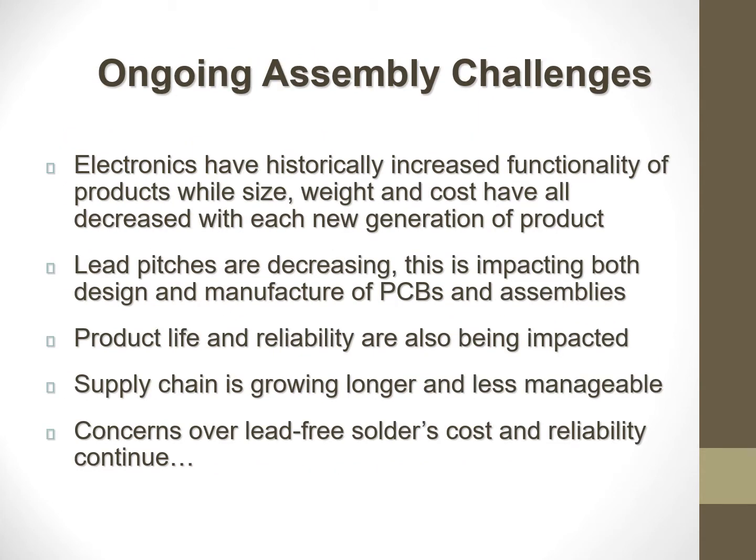There are ongoing challenges in terms of the assembly, as electronics have historically tried to increase the functionality while reducing size, weight, and cost. One of the challenges in the manufacturing of electronics today is that lead pitches are decreasing, which makes it much more difficult in terms of the design and the assembly, especially below 0.5 millimeter pitches. Product life and reliability are being impacted by choices such as lead-free solder. The supply chain is growing more difficult to manage, and lead-free is, as I said, causing some concerns about cost and reliability.